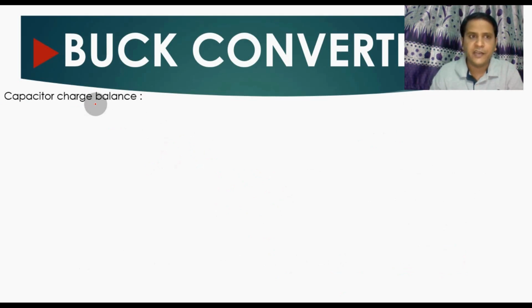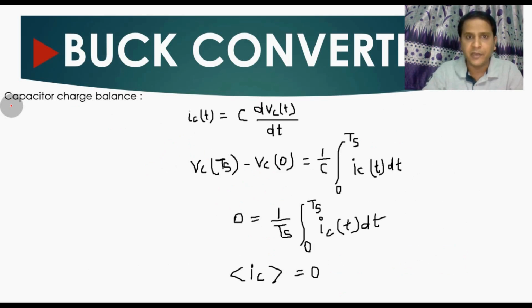Now we will understand one more very important parameter, that is capacitor charge balance. What is the capacitor charge balance, and what is the behavior of the capacitor in the buck converter, right? So this is a very important parameter we will understand now. So if you want to find out the current across the capacitor, which is given by iC over a time period t, equals C into dvC(t) divided by dt.